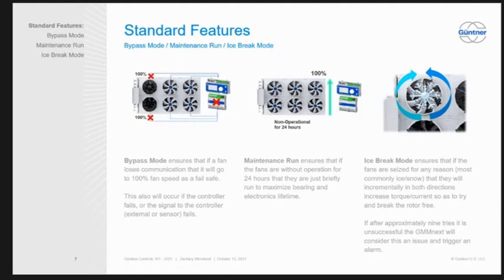The other thing that's nice about this is what some of our competitors do. Instead of running individual Modbus lines, they'll run one Modbus line and daisy chain it from fan to fan, because it's cheaper. Then you have to program the controller and address each fan individually. With us, you don't have to do that. It's a little more work on the manufacturing side, but on the user end it's easier, because if a fan fails, you just swap it out and it comes alive.